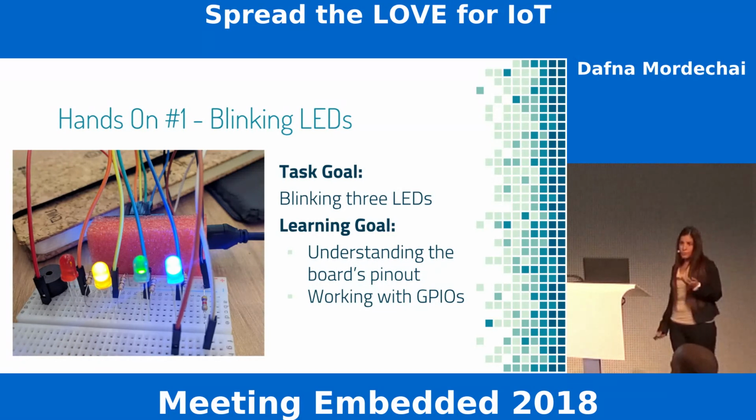So the first thing we do, we just blink 3 LEDs. They got 2 LEDs already. They got the code blinking, and they just needed to adapt it to light the 3rd one. But the actual learning goal was to look at the data sheet, to look at the board pinout, and to understand that, and for the first time, for some of them, to work with GPIOs.